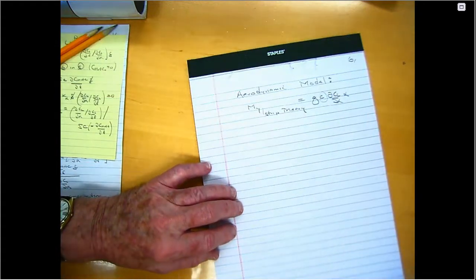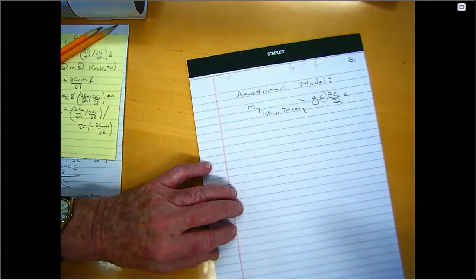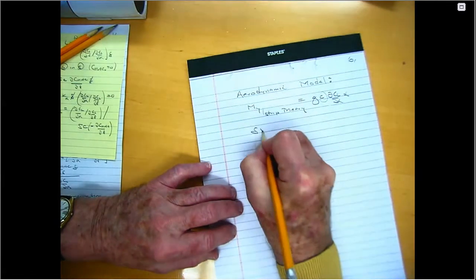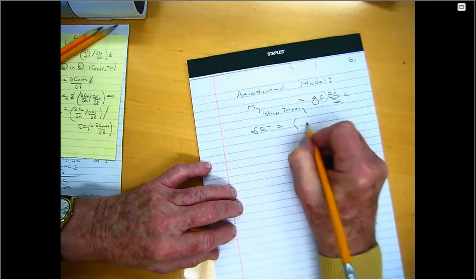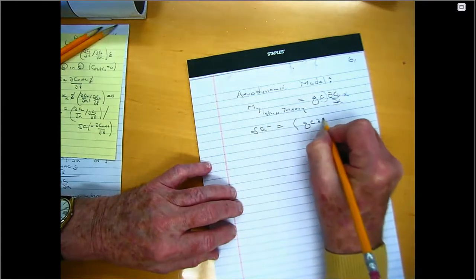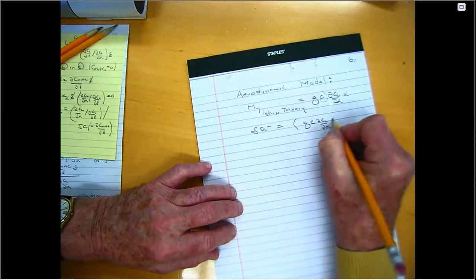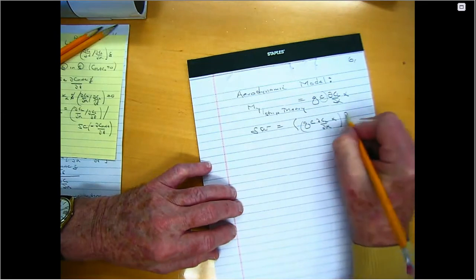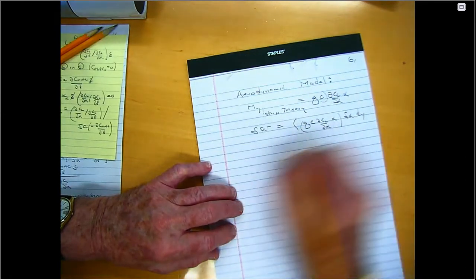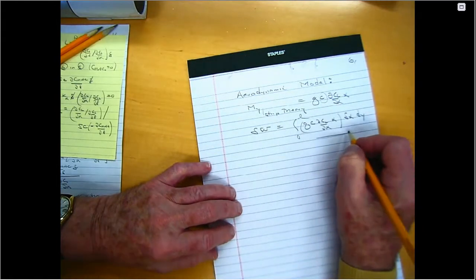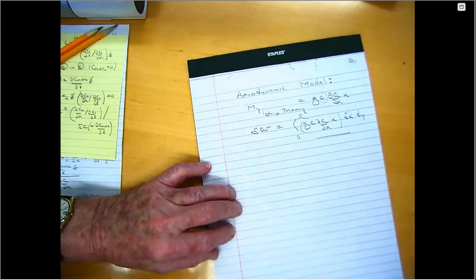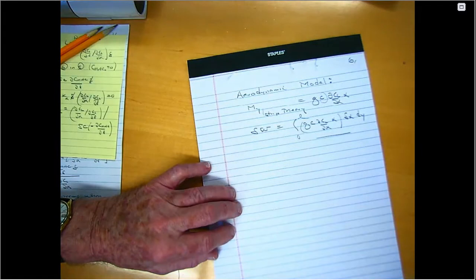So this is the moment per unit span, right? That's important. Because now when I construct the virtual work, I want to take the moment per unit span multiplied by del alpha and integrate over the span from 0 to L. Right? This is the total work done by all the moments acting along the span and integrated over the span.